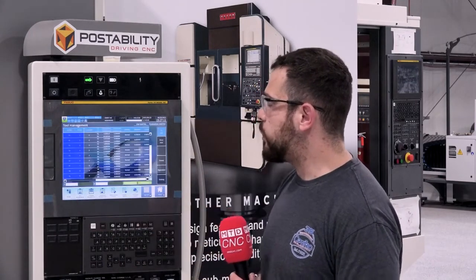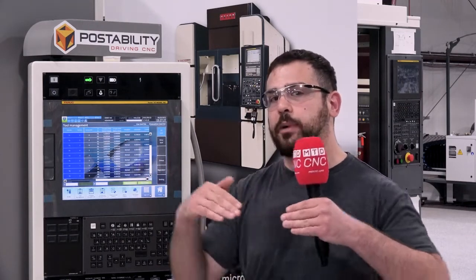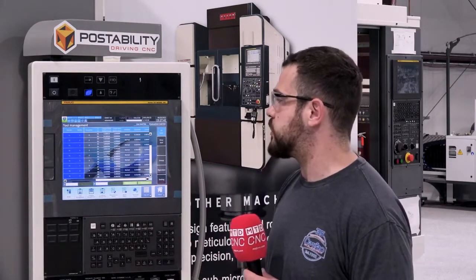The other one is this tool management. So this would be using a laser or high-speed camera to actually go and find the tool length of the tool itself. So not only does it find the tool length, it finds the runout, and in some cases it'll actually map out the profile of your cutter to a certain amount of degrees depending on how you set up. So the idea is, if you know as much information as you want on the tool, when it gets fed back to the system, your part's just going to be that much more accurate. It's a really nice system that they put together here.